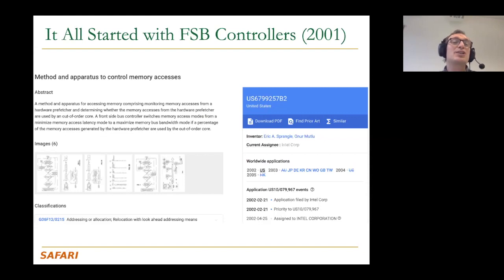They basically communicate with additional memory controller chips. And this is very scalable now, because there are many potential memory controller chips, and they essentially can have a huge amount of memory in their system. Now, of course, this comes at the cost of latency, as I said. Your latency is not as simple as you go through your memory controller on chip and you access memory. You have to go through one more chip at least to go to memory.